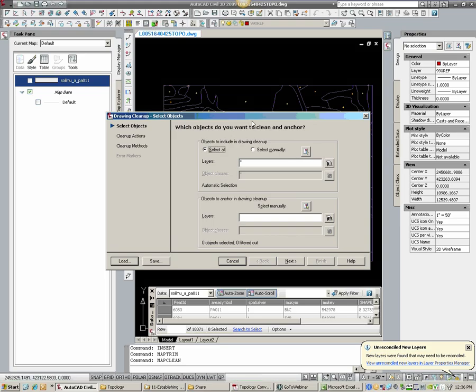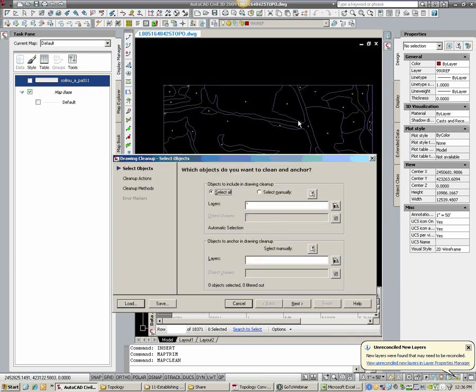And this map clean will actually, when these soils are brought in, they're closed polylines, and they're overlapping each other on the edges. And very similar, and it's not coincidence, very similar to Civil 3D parcels. You cannot have overlapping lines on the boundary. Like this boundary line here cannot have a polyline for this enclosed area and then another one to outline the enclosed area over here.